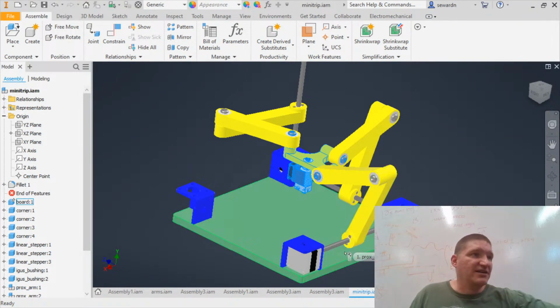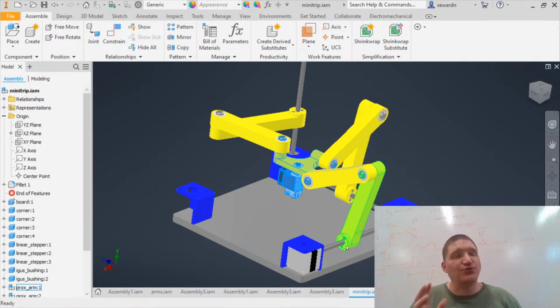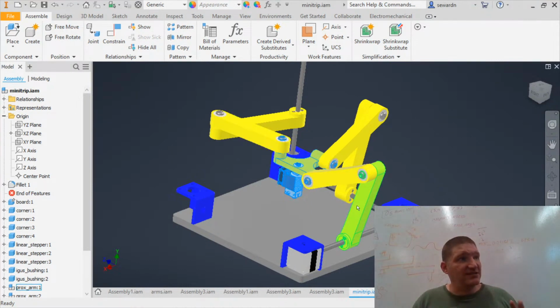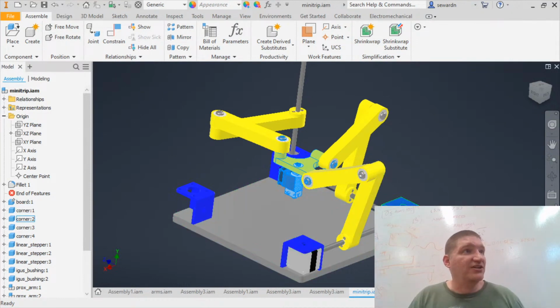And this is not a Tripteron. I mean, I'm going to call it a Tripteron, but it's not a Tripteron because whenever one of the other axes move, it will actually change my position on the screw and mess my position up. And that makes the math oh so hard. So I actually need to have knowledge at all times about where my arms are in space so I can calculate the right things. So for the simplicity of just having everything on a screw, I have to pay for that with some firmware, and I think I can pull it off. I think it'll be a super fun little project. Like who doesn't love a little cute printer? I'm sure somebody.